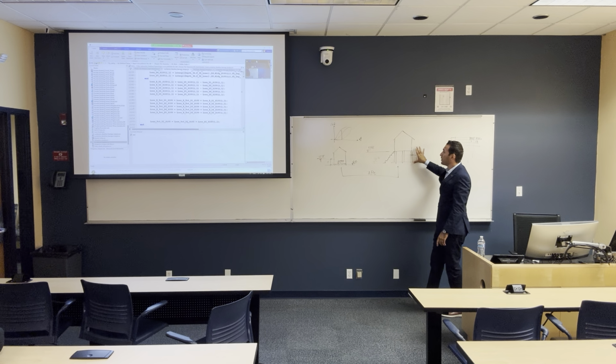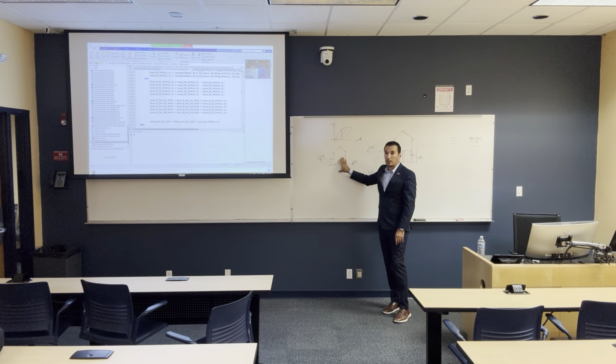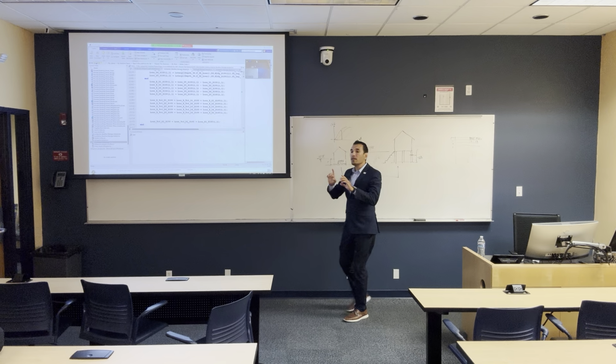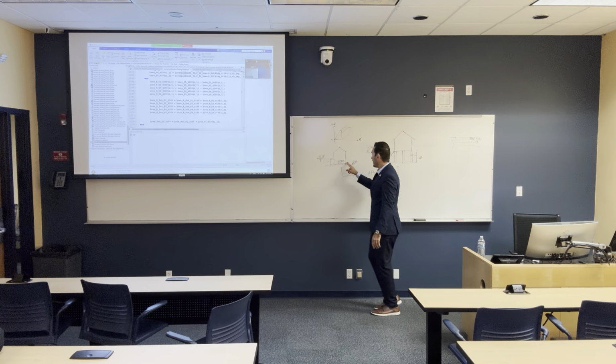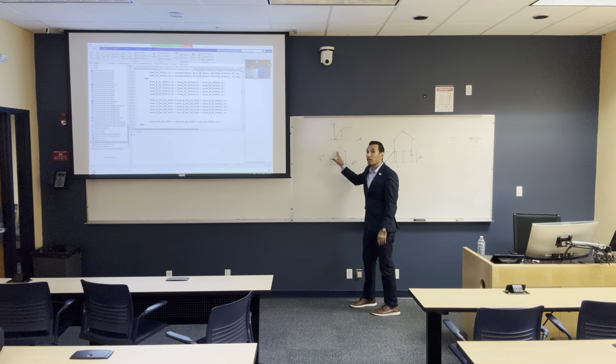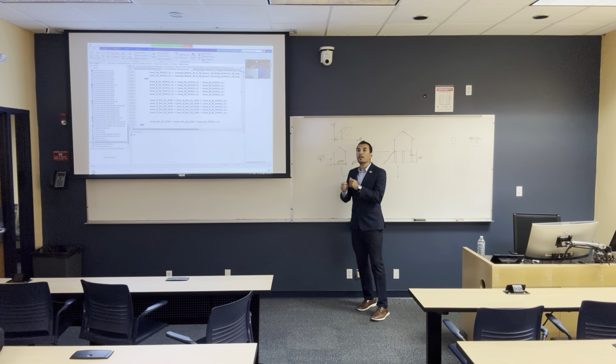I see. So this building is less exposed than this building. And when I mitigate the building, like let's say I'm going to elevate the water-sensitive components. If I have an AC, I'm going to put it in the attic. If I have electronics, I'm going to elevate them, or do something about this. Here I'm playing with the vulnerability.